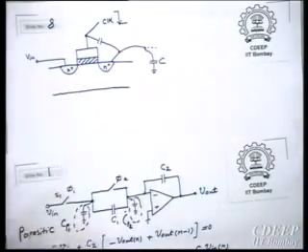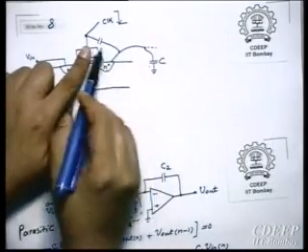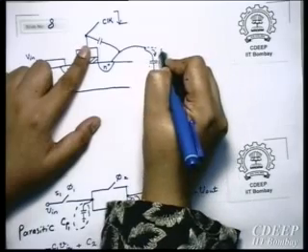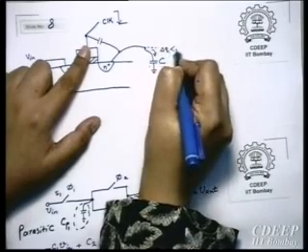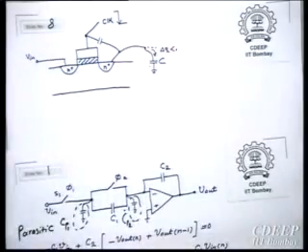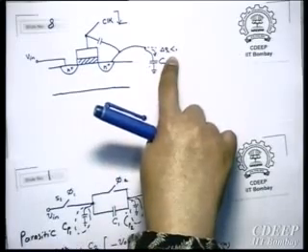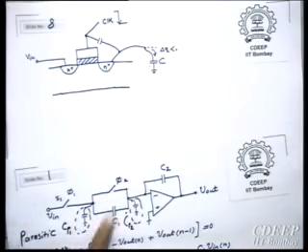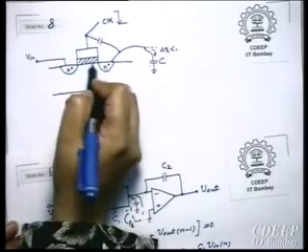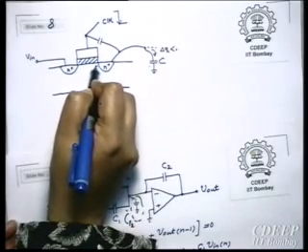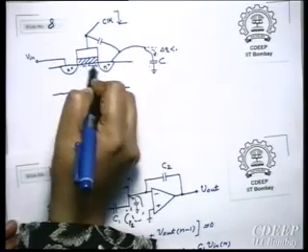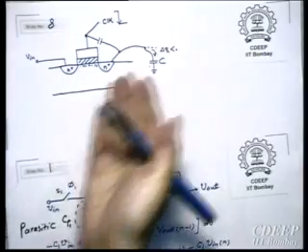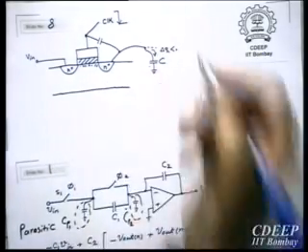At that time, there is a capacitive division here. Therefore, some charge will come here. And this charge is negative, because this is a falling edge. This will fall. Okay. So this is one delta Q which will happen when this switch is opened before this switch gets closed. The second thing is this was on, right? So charges which are stored here need to get discharged. Some part of these charges may come into this capacitor. Therefore, we will have 2 delta Q.